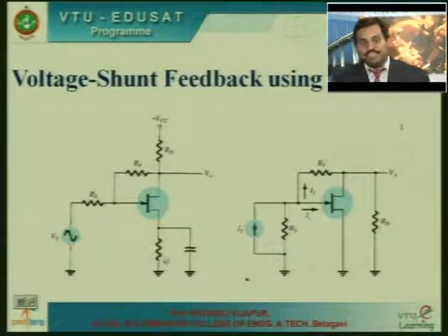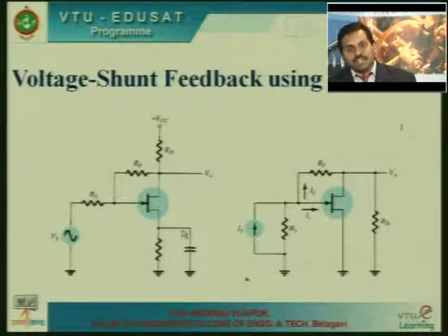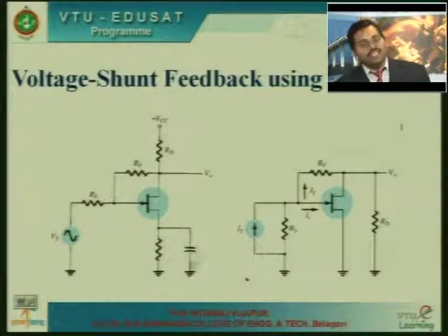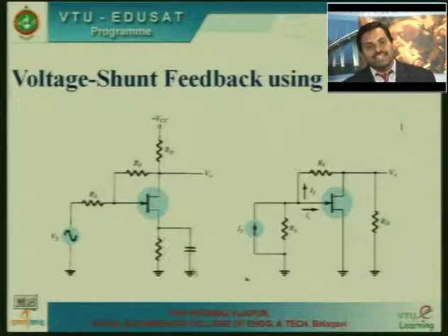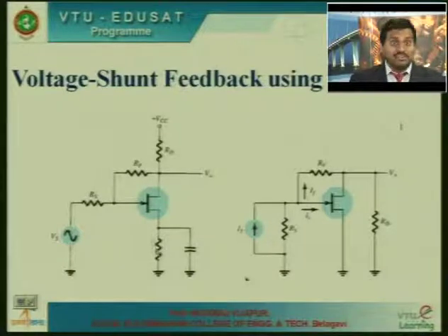You can observe that we have not given any value to this resistance. This is simply because it gets bypassed via a capacitor, because a capacitance acts as a short circuit for AC signals. During amplification, the AC signal will prefer the path of the capacitance, that being the low impedance. So it gets short circuited, and this resistance is ignored in the calculations of feedback.